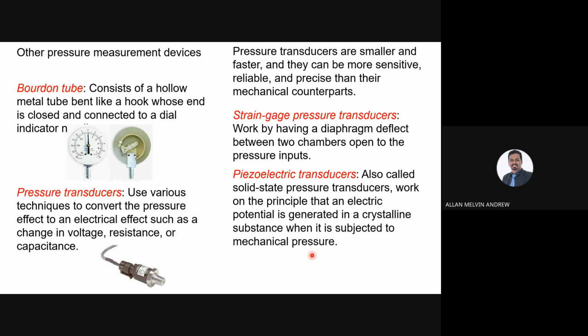If you give mechanical pressure to the piezoelectric transducer, it will generate an electrical signal. More or less all these are the same because all are pressure transducers, but the differences are in the mechanism of how you give the pressure and what it converts to, whether voltage, resistance, or capacitance.